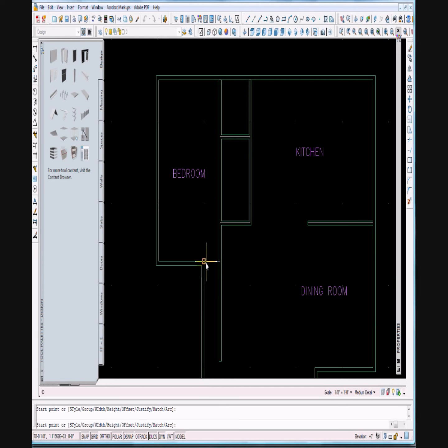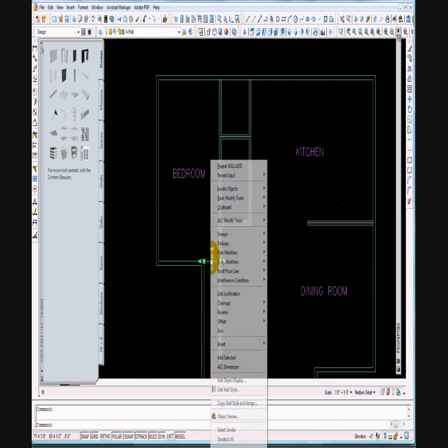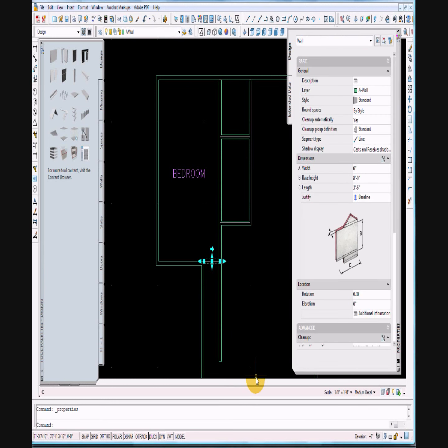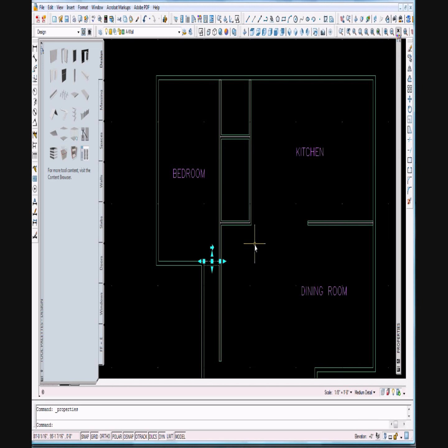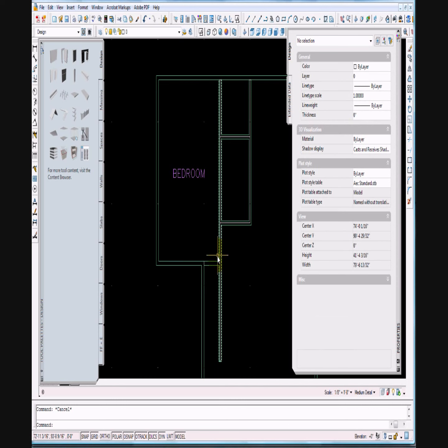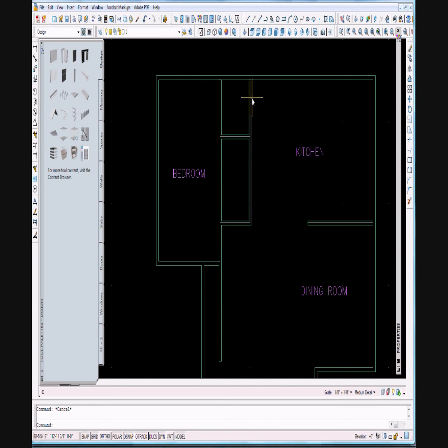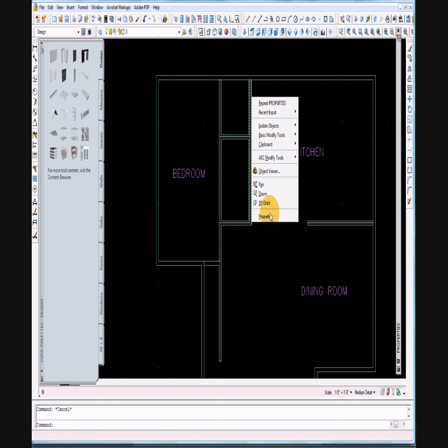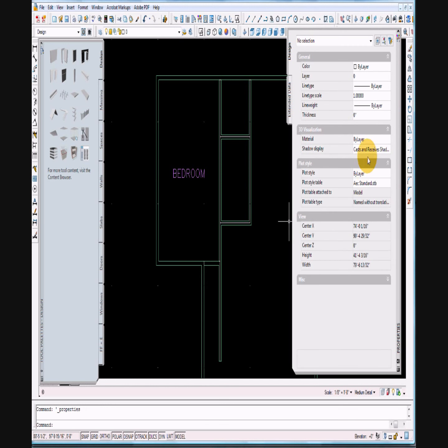The last wall is a little area at the bottom of the bedroom, and if you notice when you select it, it's probably not going to go in correctly. So right click on the item, the wall, and you want to right click at the very bottom, go ahead and click properties. And the justify, right now it's baseline, we want to go left, and if it decides to be on the right for your computer, just make sure that that wall is smooth. And then go ahead, you can see you can do that to all the walls.